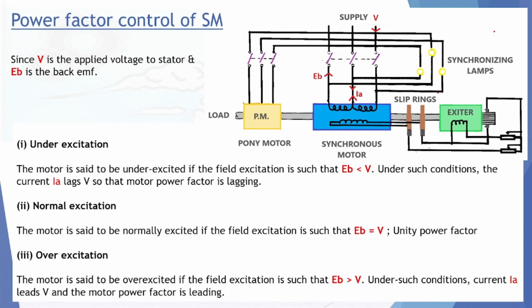Actually, it is not that harmful a situation because it acts as a normal synchronous motor. The only thing is that there is a danger if you continue to use it, because there is no use, only power loss, and the other running healthy generator may get overloaded if there is any problem. And the major risk is, if any safety is activated from the mechanical side of your prime mover, it won't stop. Even with the fuel cut off, it will not stop because the alternator will drive the prime mover. Okay, I will be discussing that in the generator protection session.